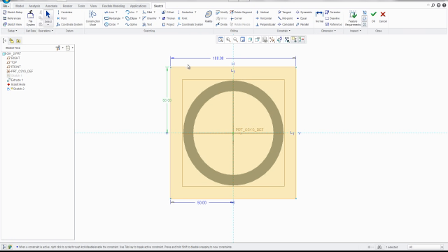The reason for that is when I was creating the rectangle, notice I was given a constraint of L1 on my horizontal line and L1 also on my vertical line. So if I were to redefine my horizontal line from 100 to say 120 or 130 or whatever I want to pick, it's automatically going to resize the vertical line as well. So both of these lines are defined as L1, and that goes for the rest of the square.